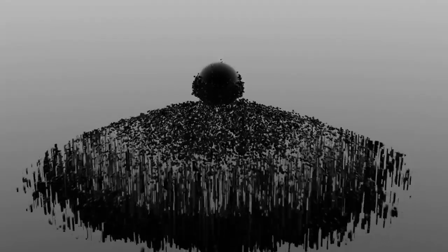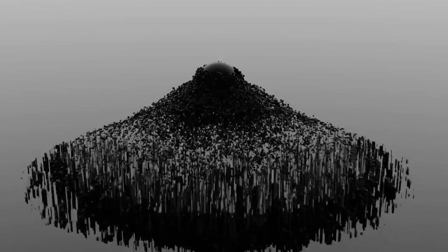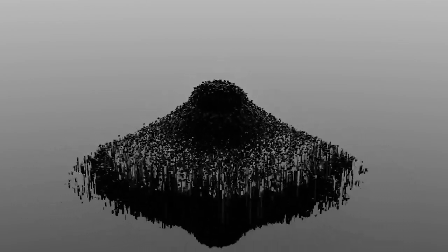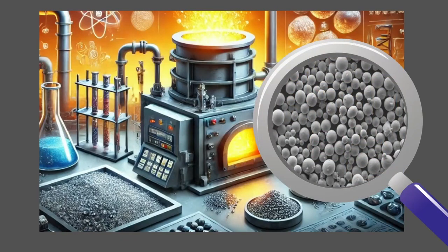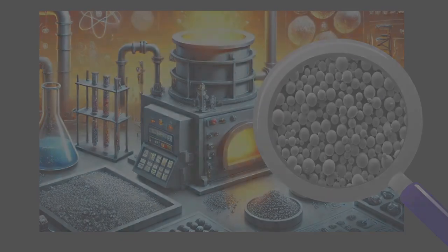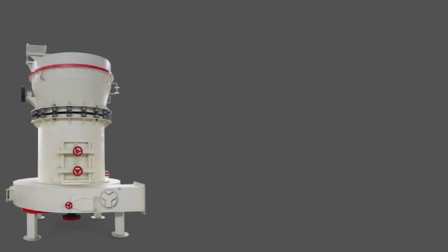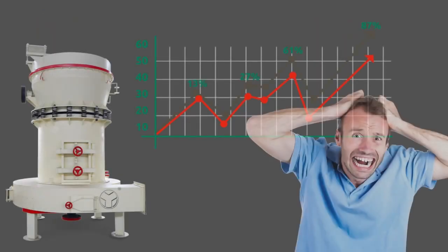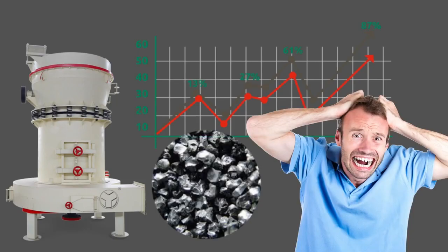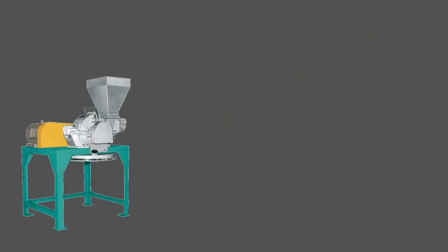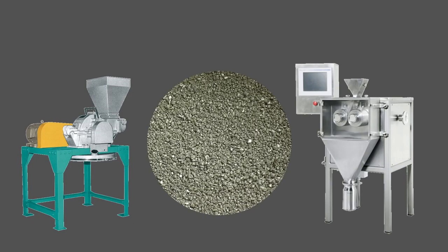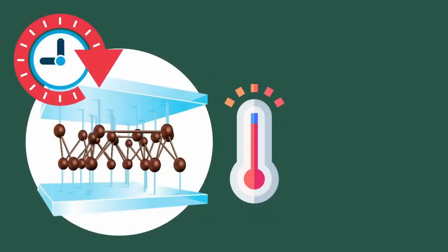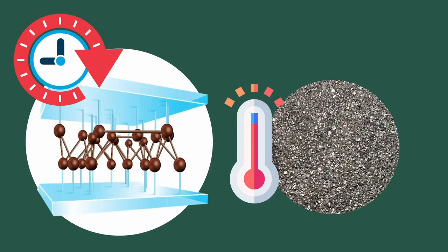This imposes stringent requirements on preparation of charged material, the constituents of which should be finely dispersed and thoroughly mixed. Various types of pulverizers and mixers used in addressing these tasks do not meet the existing production requirements. Therefore, powders of the required grain size are produced by sieving on vibration screens of various designs. Mixing of charged material constituents is time-consuming, since the properties of finished products largely depend on how uniformly the constituents are distributed.